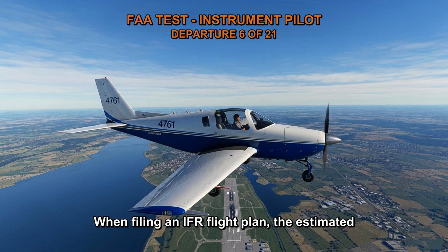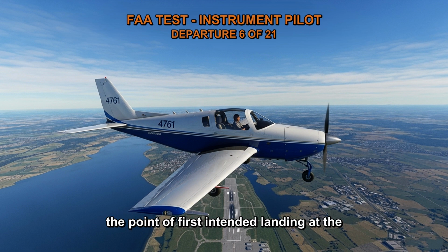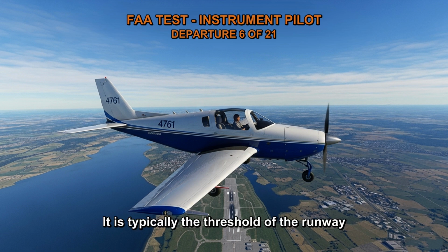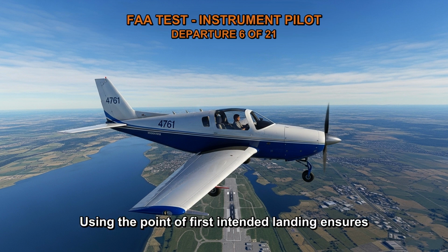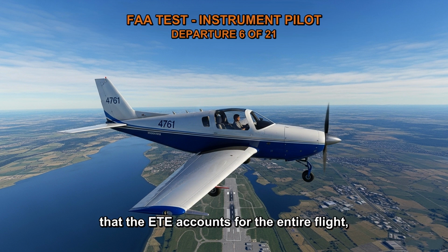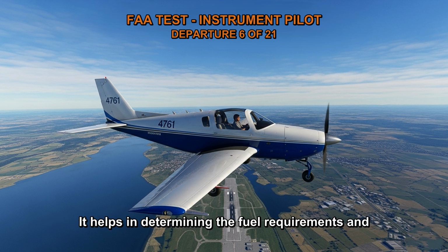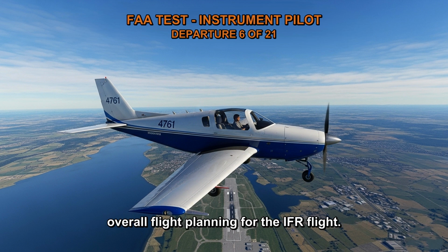When filing an IFR flight plan, the estimated time en route, ETE, is calculated based on the point of first intended landing at the destination airport. This is the point where you expect to land and complete your flight. It is typically the threshold of the runway or a specified point on the airport. Using the point of first intended landing ensures that the ETE accounts for the entire flight, including any anticipated approach and landing procedures. It helps in determining the fuel requirements and overall flight planning for the IFR flight.